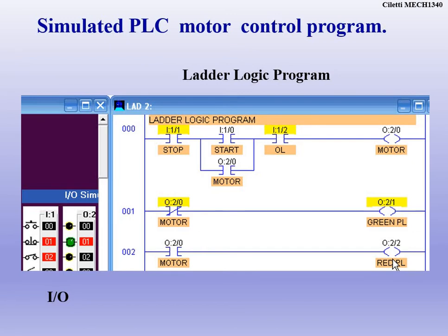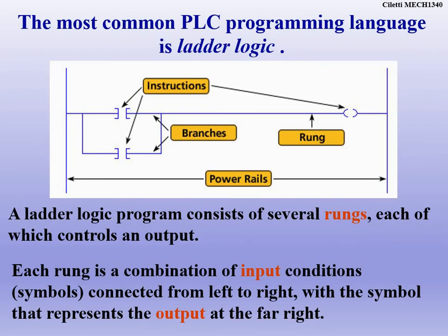So if we take a look at PLC language and our ladder logic, each one of those contactors, those are our instructions. So shown here, the 2 instructions on the left, those are normally open contactors. On the right, that's our coil, usually turning on our motor or light or something like that. Those are our outputs. So we have input instructions and output instructions.